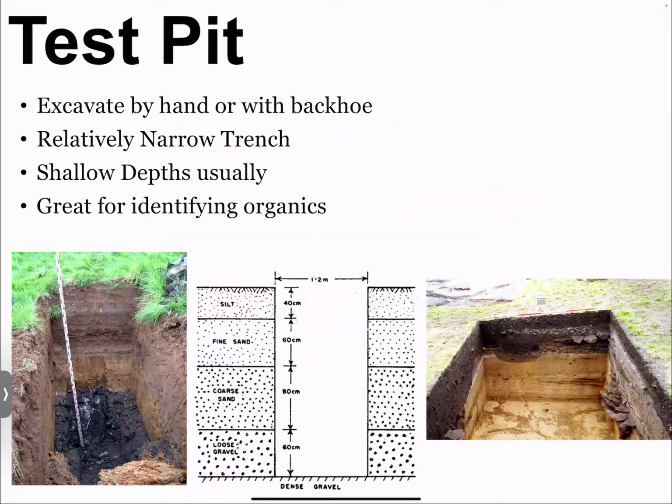That's exactly what it sounds like. It's very easy to go out with an excavator, like you see on this top left, and just do one little streak of the excavator to see what type of soil there is. This is really helpful when we're looking for potential borrow pits, like where is the soil on our site that we can use for fill dirt? You know, if we need to build an embankment 100 feet that way, can we use this here?